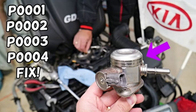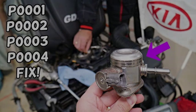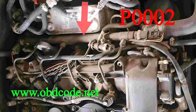Code P0002 is a diagnostic trouble code, DTC, that indicates a problem with the fuel volume regulator control circuit. This circuit is responsible for controlling the amount of fuel that is delivered to the engine. When the PCM detects a problem with this circuit, it will set code P0002. There are several possible causes of code P0002, including a faulty fuel volume regulator, a problem with the wiring or connectors to the fuel volume regulator, or a problem with the PCM.